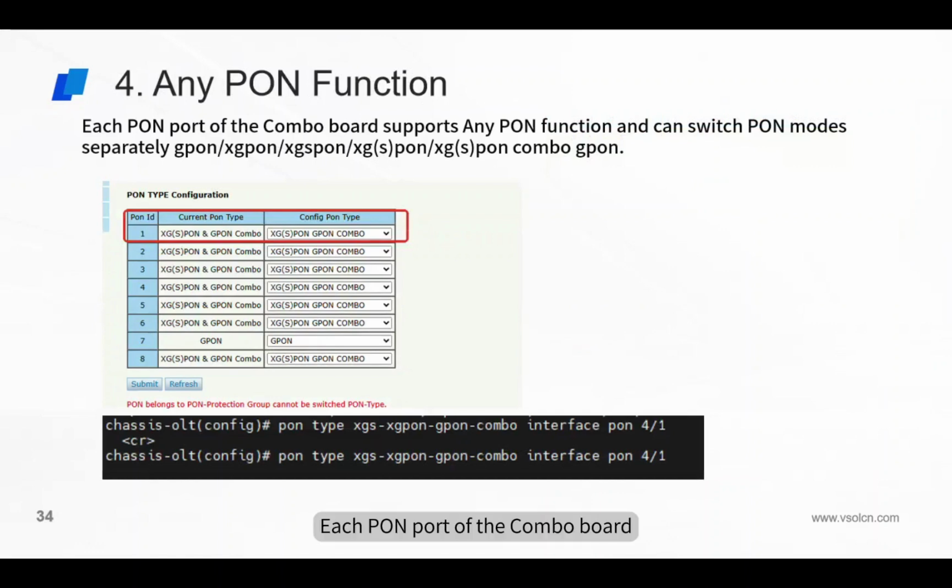Each PON port of the combo board supports any PON function and can switch PON modes separately: GPON or XGPON or XGS-PON or XGS-PON combo GPON.